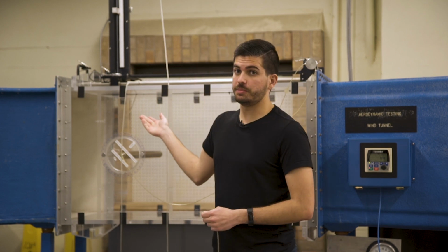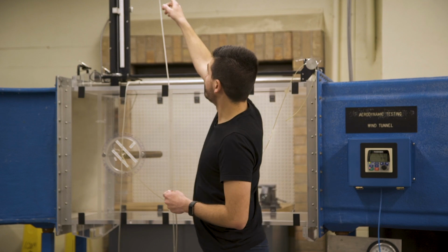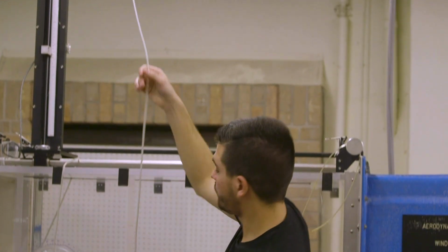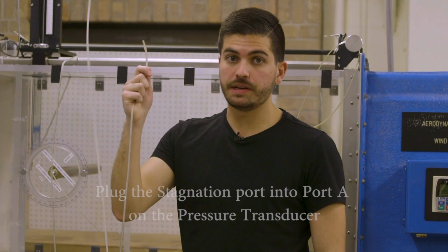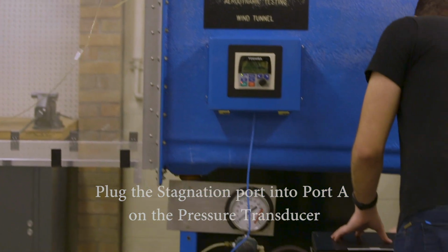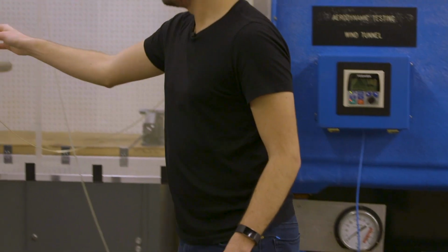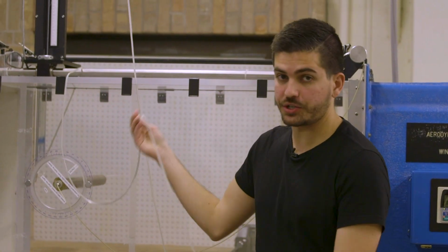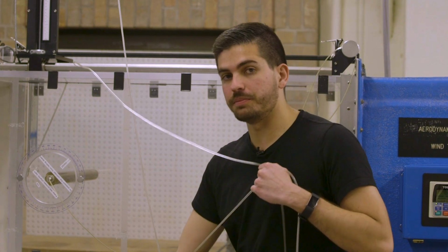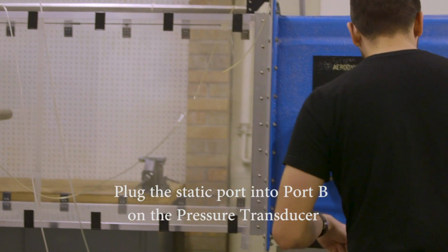The pitot-static probe has two different ports. One of them measures the stagnation pressure, and that one is attached to a line that comes out of the top of the stem. So if we follow this line down, we can plug the stagnation port into port A on our pressure transducer. The other line measures the static pressure, and that comes out of the side of the pitot-static probe. And that goes to this line, and we'll plug that into port B.